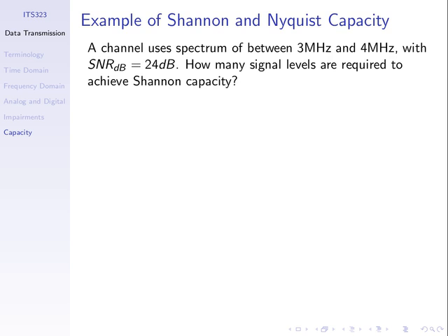let's write it differently. The SNR in decibels is 10 times the logarithm in base 10 of the ratio of two powers, the signal divided by the noise. So if this is the absolute value, the value in decibels is just the log of that multiplied by 10.